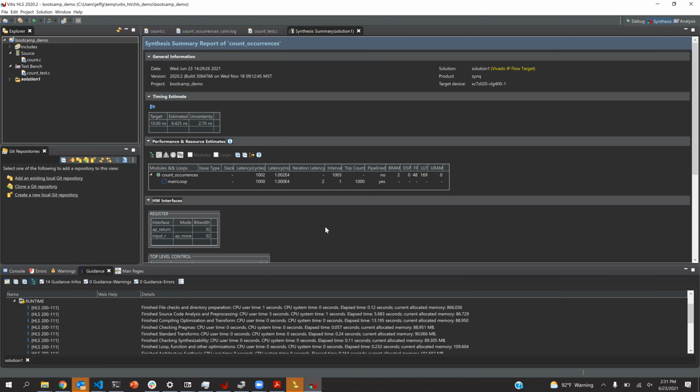And you don't know if the routing is going to go directly or go winding around. If you put this in a design with lots of other stuff and it's really congested, it's harder to find direct routing paths. So until you actually place and route it in Vivado and wait the time to do that, you don't really know how long those paths are and how fast you can run.